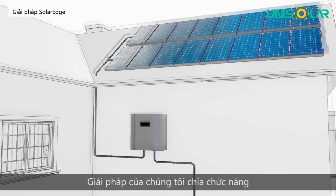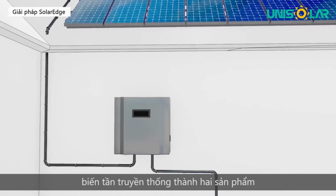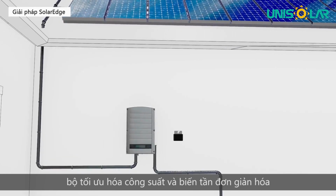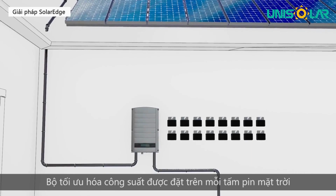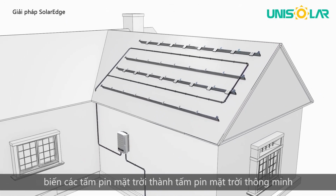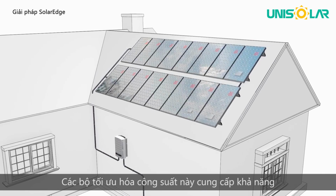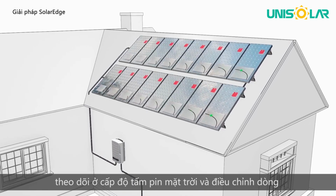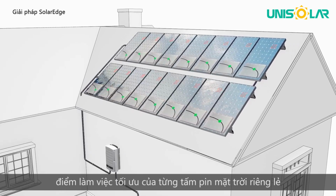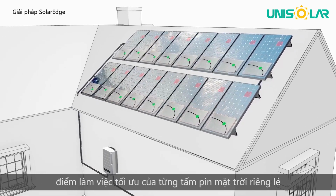Our solution splits the traditional inverter functionality into 2 products: the power optimizer and a simplified inverter. The power optimizers are located on each panel, turning the panels into intelligent panels. These power optimizers provide panel-level tracking and real-time adjustments of current and voltage to the optimal working point of each individual panel.